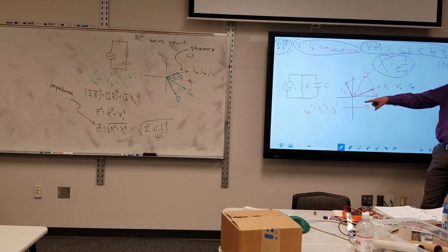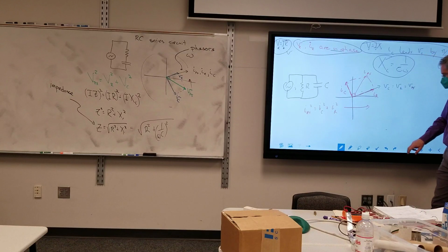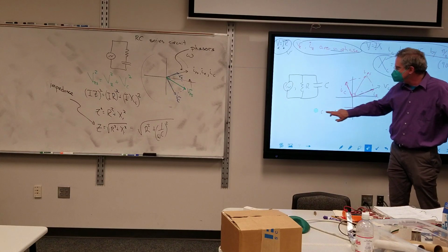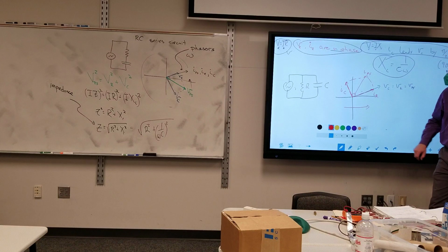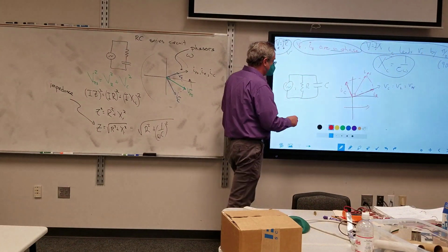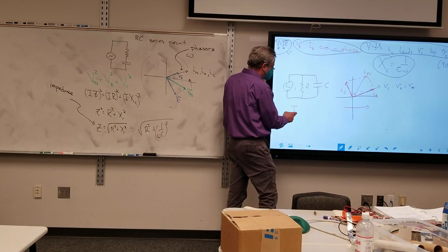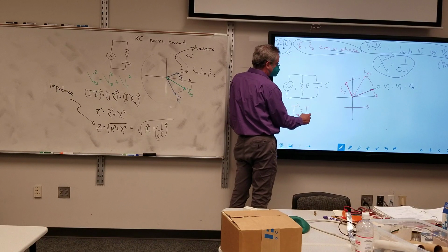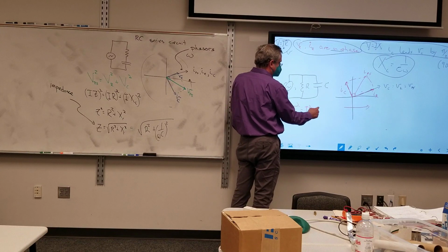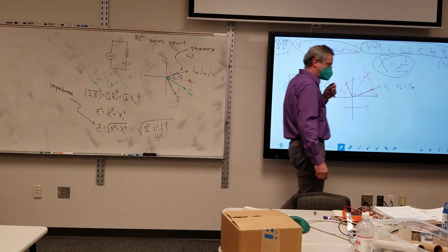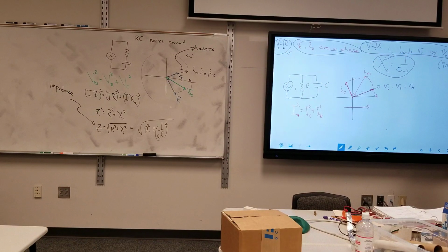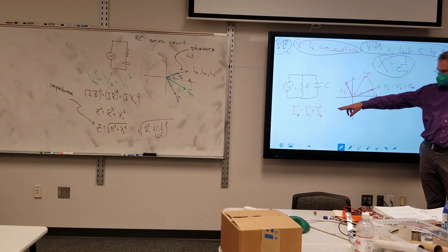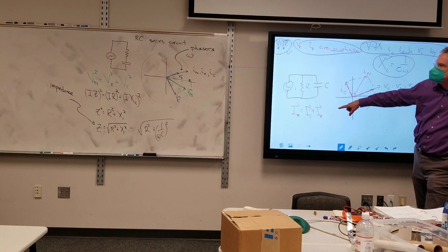Because remember, what I added here, I'm going to rewrite this right here. This is misleading. What I added were the magnitudes there. So this actually should be capital I from the power supply squared is equal to capital I from the capacitor squared plus capital I from the resistor squared. With the lowercase values, it should be IPS equals IC plus IR. All right, good. Yeah. When you're adding phasors, it's the capital letters, which I did over there correctly.